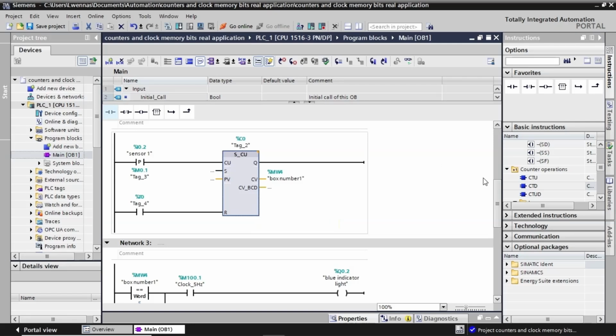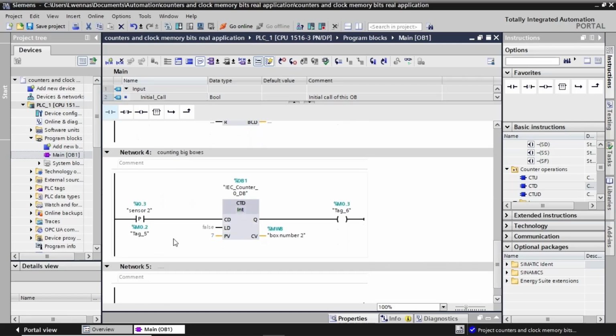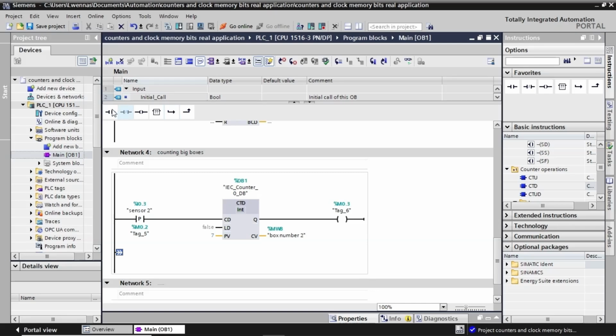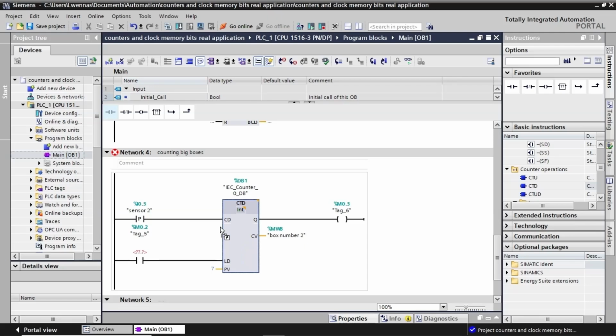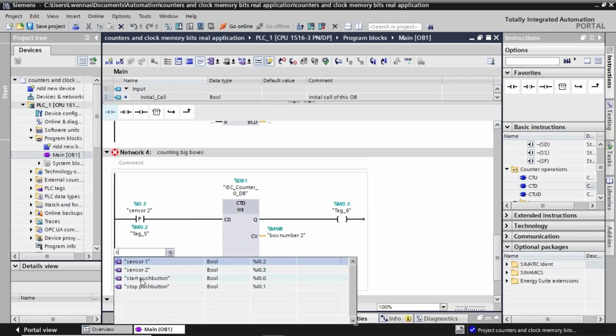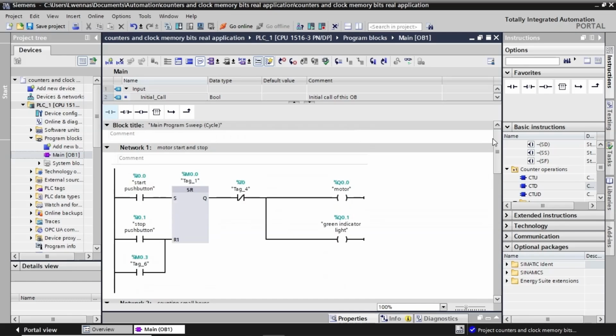As to the countdown counter, we need to reload the preset value. Ideally, we make the start push button seeing the fact that the counter output deactivates the process. So, at each start the preset value is loaded. However, beware this remains valid in a perfect environment with no failures altering the process such as power failures that would reinitialize the counter. In this case, other considerations and parameters will enter into the game which are out of the purpose of this course.